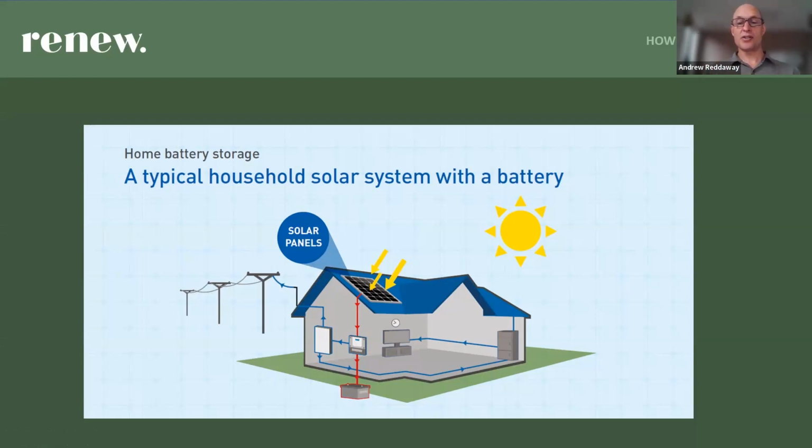It can be a cheaper way to set it up, because you're not paying for two inverters. The power that you can get out is limited though, because if, let's say you had a 6.6 kilowatt solar system, it might be a 5 kilowatt inverter. So that's the maximum that inverter can put out, 5 kilowatts. Even though your battery could put out more, let's say you're getting 4 kilowatts from your panels and your battery could put out, I don't know, 6 kilowatts, you might think, oh, great, we can get 10 kilowatts, but you've got that bottleneck of that 5 kilowatt inverter.